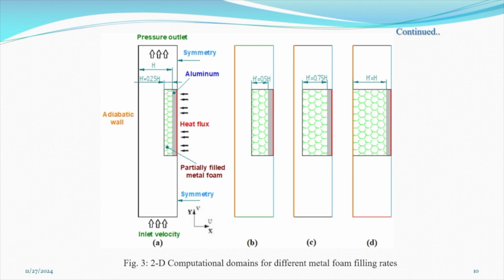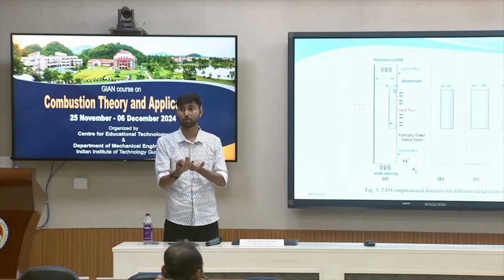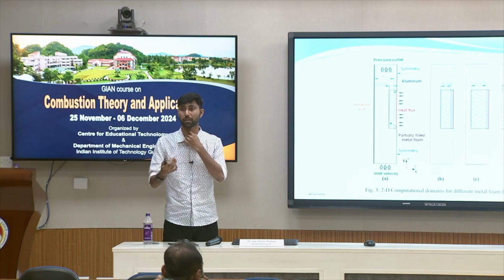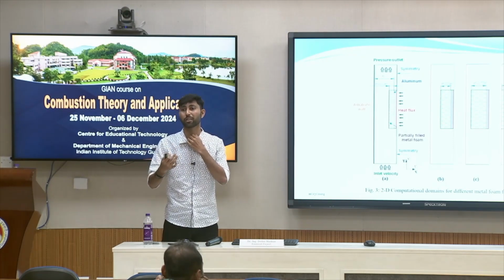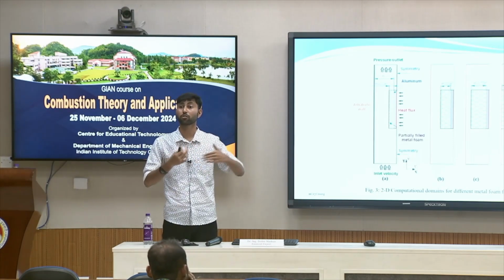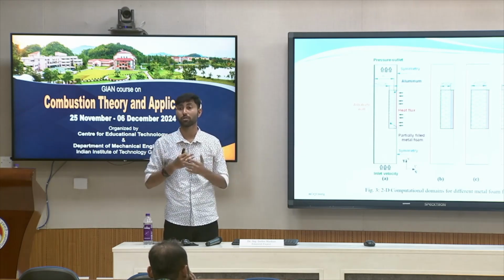And here you are using air. Yes. If you think in terms of heat exchange purposes, then water can also be used, and that further analysis can be done. So we can use water, as well as, as I told you, nanofluids. Basic water along with cuprous oxide or copper oxide, aluminum oxide, iron oxide, like that nanofluid can also be introduced. So further enhancement is possible.